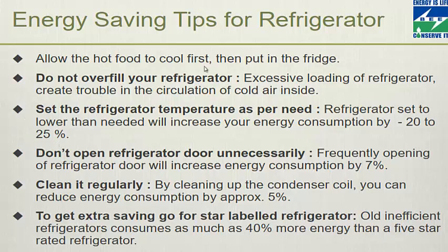Do not open the refrigerator door unnecessarily. In that case, it has to consume a lot of power to cool the equipment inside the refrigerator again and again. This will increase energy consumption by 7%. Clean it regularly. By cleaning the condensing coil, you can reduce energy consumption by 5%.